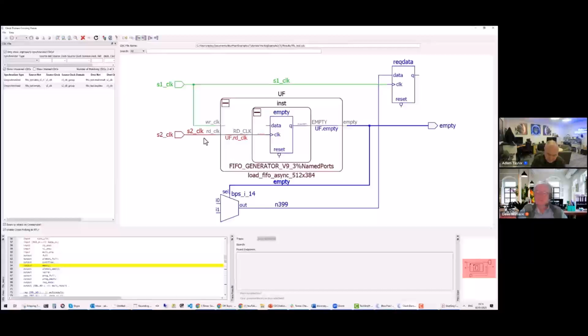So this is a really important point, and a really nice one, because the first example shows how you can detect and find coding issues that people make while they're doing code. This issue actually identifies an example where we're working with IP and the IP's incorrectly being connected up. And in that incorrect connection, it's introduced a CDC issue.